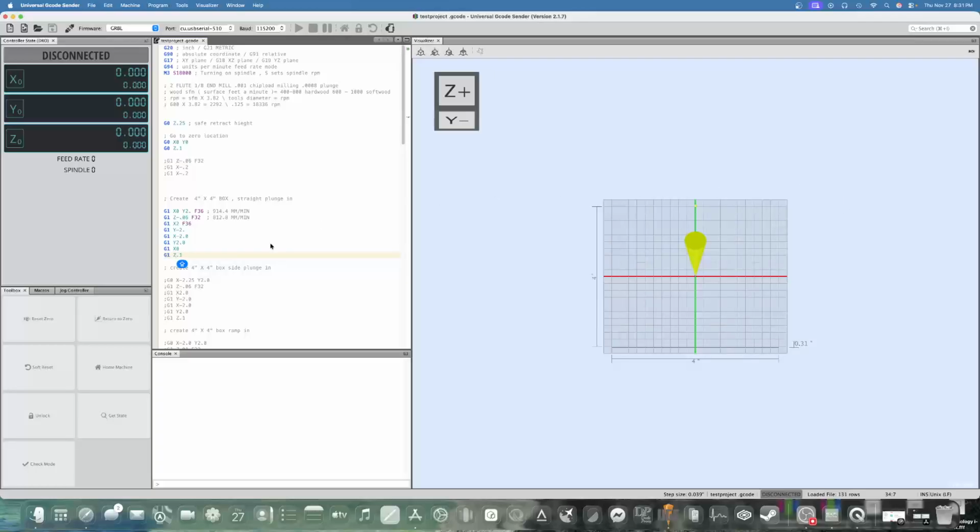You could simply go in here, omit that line right here where it's retracting out, but you could go here, hit copy, paste as many times as you needed by incrementing. Like this is 60 thousandths, then I would change that to 120, then 180, until I got through the thickness of whatever it was I was cutting that contour out of.